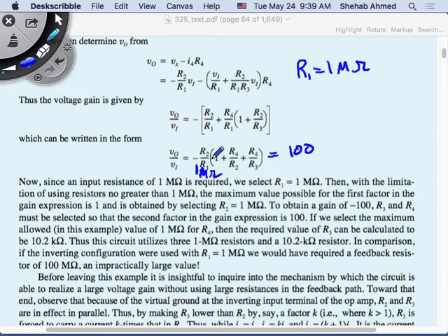So obviously this is not going to help. How about if I choose R2 to be also 1 mega ohm? So I made this 1. The stuff outside is 1, okay? At least I don't make it small, so that I multiply whatever I came up with inside these brackets by something less than 1. This has to be 500 for this to be 0.2, for example. I have to make a gain of 500 here, right? So I already fixed R2 to 1 mega ohm.